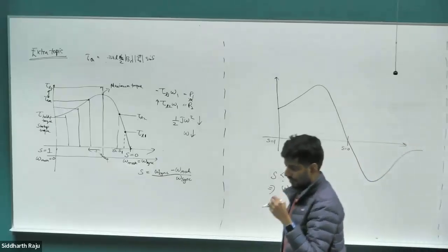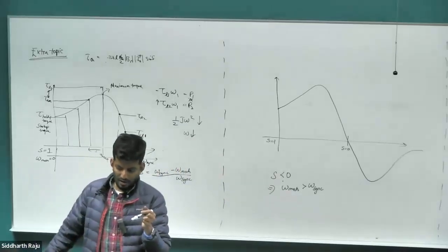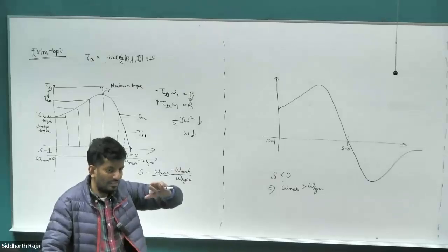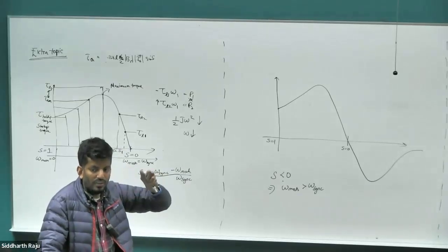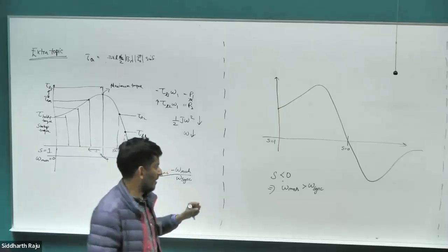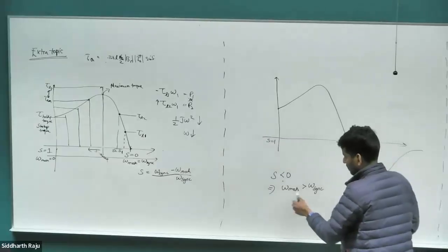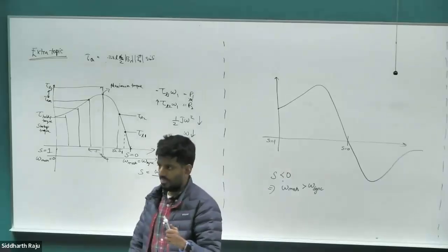We have seen something similar before in the case of the permanent magnet synchronous motor, where our rotor magnetic field started to lead the stator magnetic field. In that case, it went from motoring mode into generation mode, where we are converting mechanical energy into electrical energy. Same thing happens here. When the mechanical speed is greater than the synchronous speed, we end up going into generation mode.